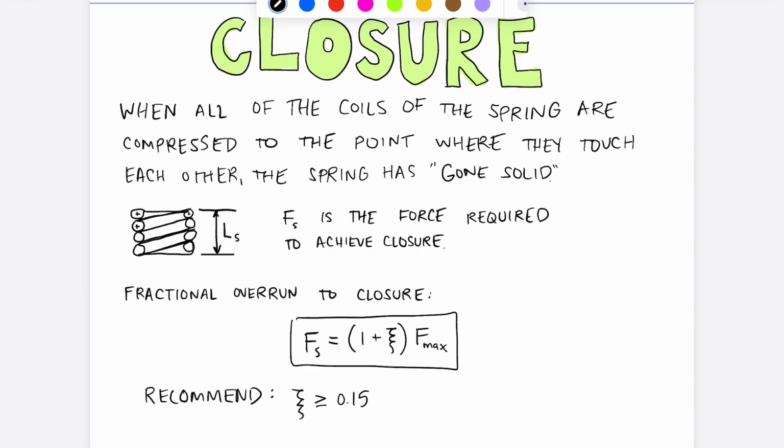And those residual stresses are opposite in direction to those that will be induced in service. So this can be very advantageous in the case where you need high strength. So especially when we have energy storage uses for the spring or applications, it can be very useful.